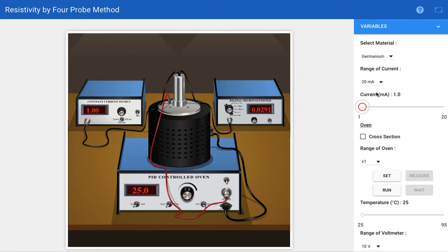Fine. However, if I click on to the 200 milliamperes portion, then in this the difference will be 2. So the first value is 1, the second one will be 3 milliamperes, then it will be 5 milliamperes, then 7. So this is up to you what range you want to choose. For my experiment, I'll be choosing 20 milliamperes range.